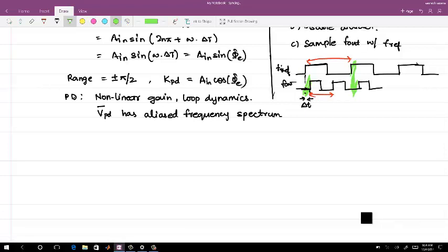It doesn't. So there are two kinds of analysis which happen for a PLL. One is time domain analysis, where you do not consider phase, you always go with an absolute delta t. Interestingly, let me just show this part also. Let's say I divide this clock by 2. If I divide this clock by 2 and the divider has no delay ideally, did the delta t change between the divided clock and the reference clock?